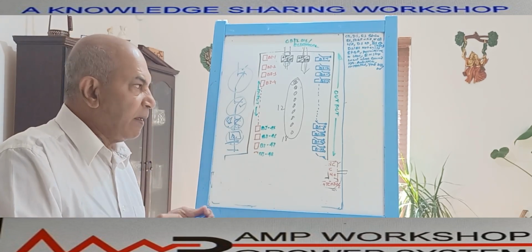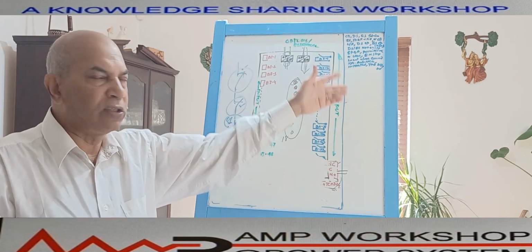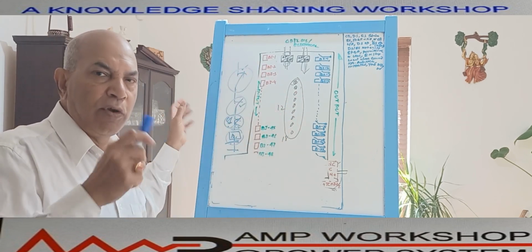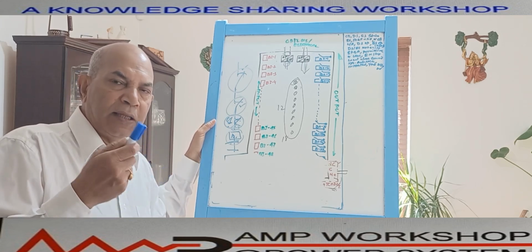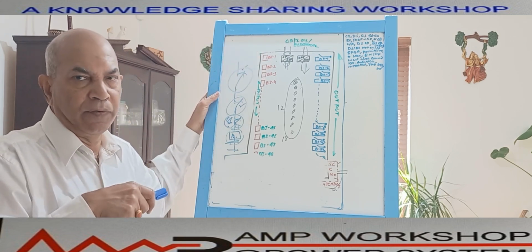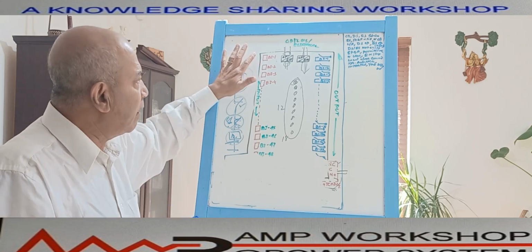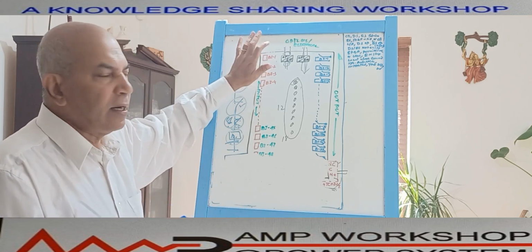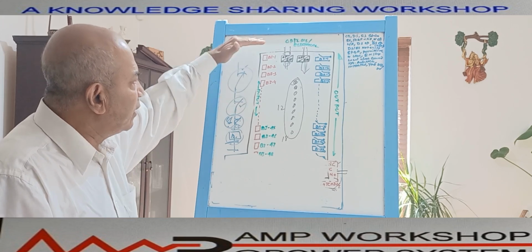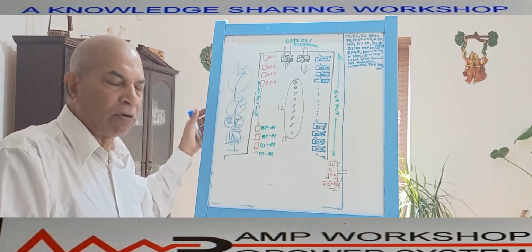That's why we bring the breaker status, disconnector status, earth switch status, and lockout relay status inside the relay. Then we can make the relay decide whether it is on. When this is not on, it means it is off, like a logic gate, an OR gate or NOR gate. If the binary input is high, that is the on state. If the binary input is not high, then it is the off state. In this way, we can use the binary input in the digital relay, in the switchgear control system.